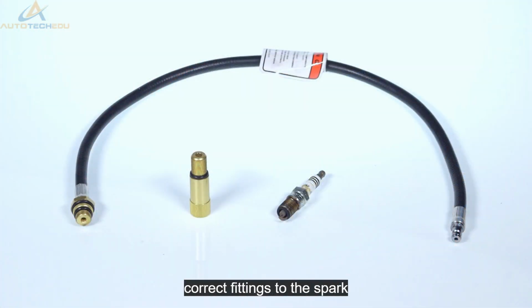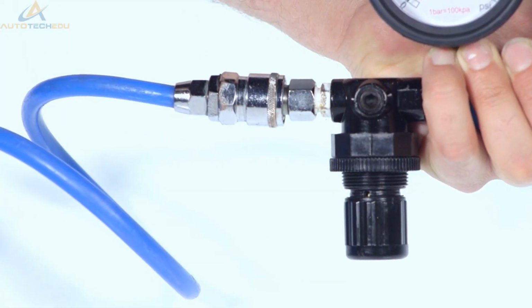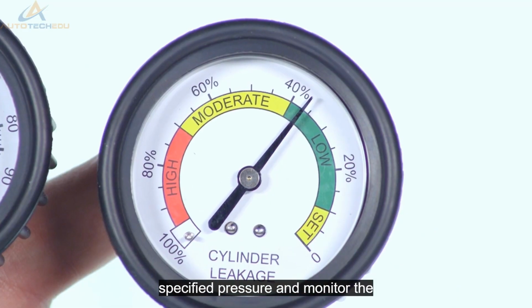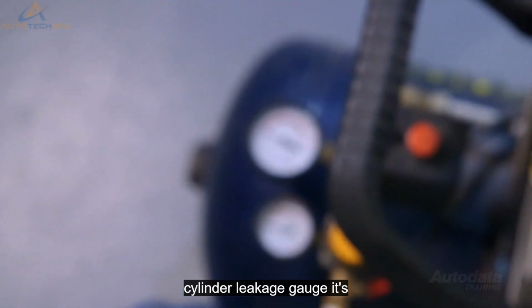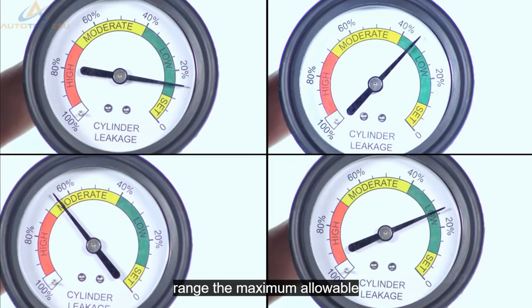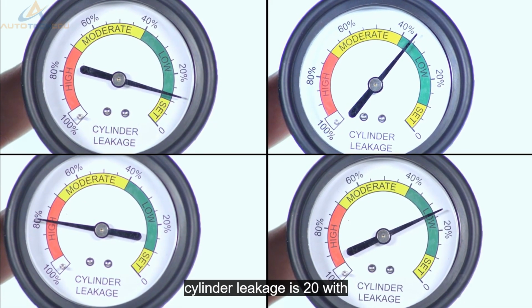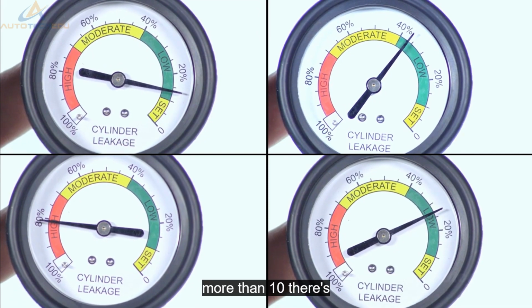Install the correct fittings to the spark plug thread and connect compressed air to the leakage tester. Set the regulator to the specified pressure and monitor the cylinder leakage gauge. It's important to have the correct air pressure supply as the leakage gauge is calibrated to operate in a specific range. The maximum allowable cylinder leakage is 20%, with variations between cylinders of no more than 10%.